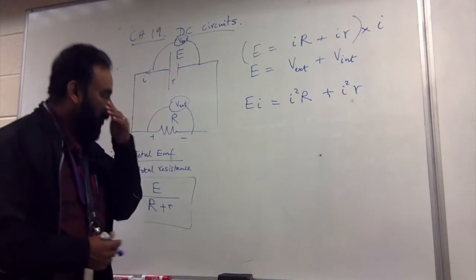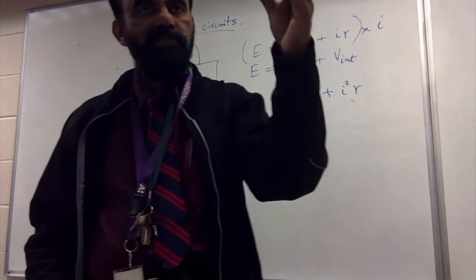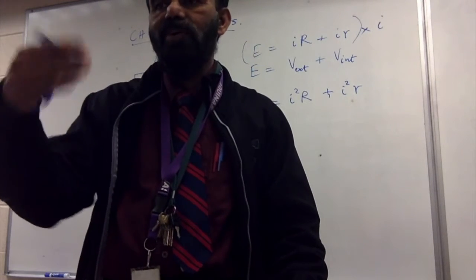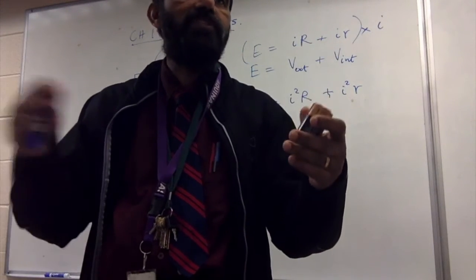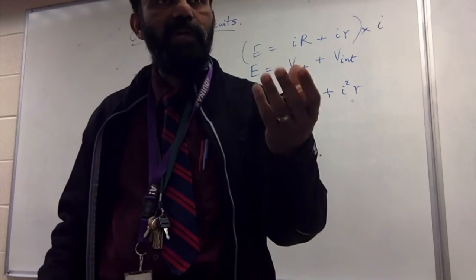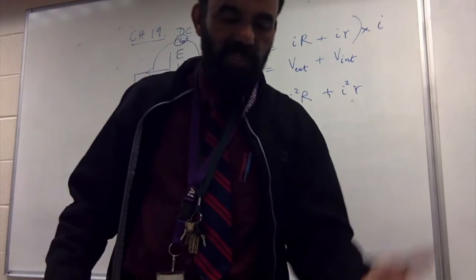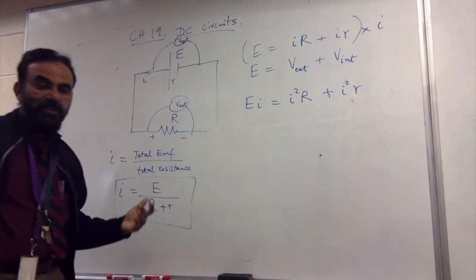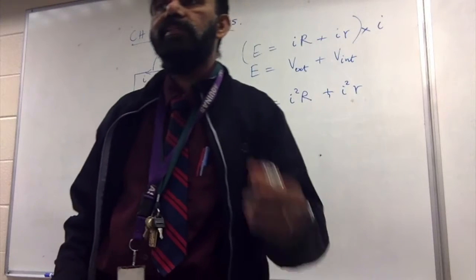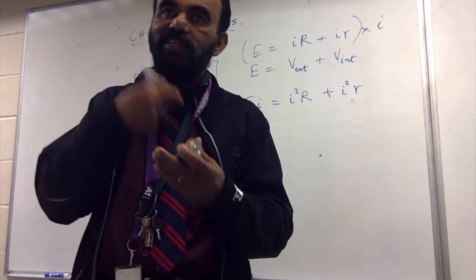All right, so anyway, the internal resistance of this one is supposed to be on the lower end, but as it ages, or as you start using it, its internal resistance will start changing, getting bigger and bigger. And when it becomes bigger and bigger, the same cell cannot be used for a certain application. And so that's when you say, oh, the cell is kind of dead. Well, the EMF never dies. The EMF stays intact, 1.5 always. But what actually changes is the internal resistance.